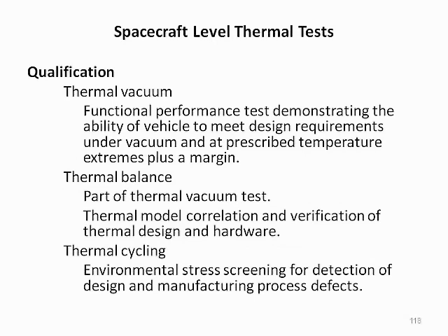At the qualification level, thermal vacuum, thermal balance, and thermal cycling are performed, typically in one integrated test. In thermal vacuum phase, functional performance tests demonstrate the ability of vehicles to meet design requirements under vacuum and at prescribed temperature extremes, plus a specified margin. In the thermal balance phase, data are gathered for thermal math model correlation and verification of the thermal design and hardware. In the thermal cycling phase, temperature cycling provides environmental stress screening for detection of hardware design defects.